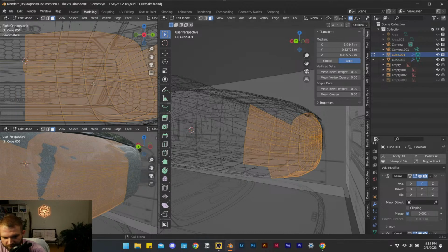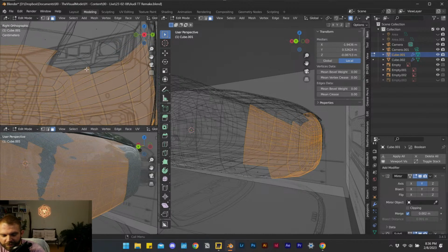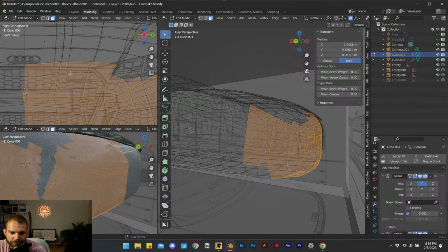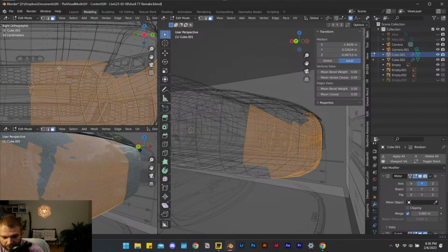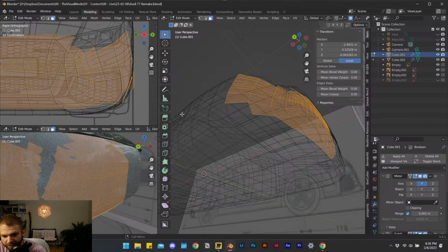so now we have that selected. We want to separate it out. Oop, I just noticed another couple that I don't want here. Yeah, see, this is where it gets a little weird, how the nose is kind of pinched in. And this is all because I offset that front of the box. If you want to check that back live stream on how that topology came to be, which might be working a little bit against me, but at this point, I think I can work around it. Well, for next time, topology is definitely something I'd want to look into a bit more and be careful and mindful of, so I don't have to spend time cleaning up like I'm going to have to right now.